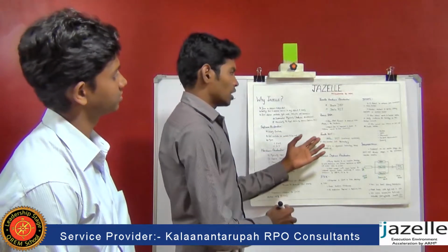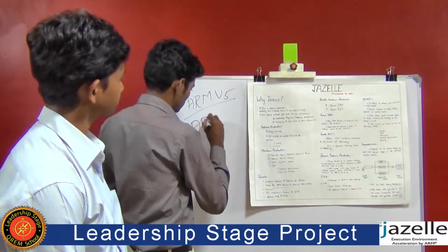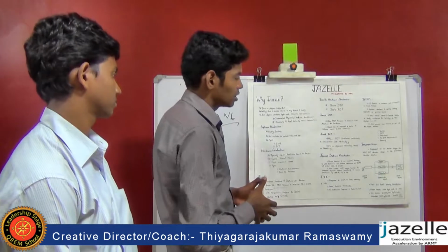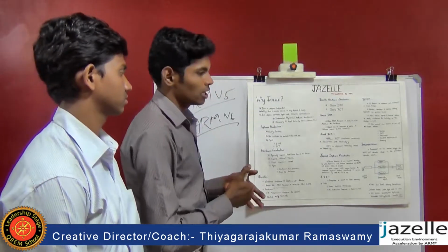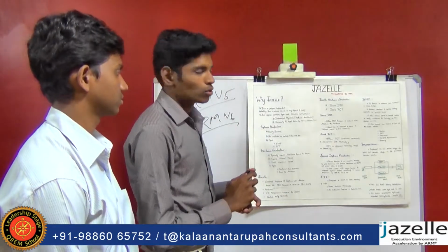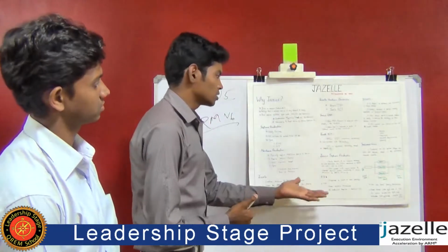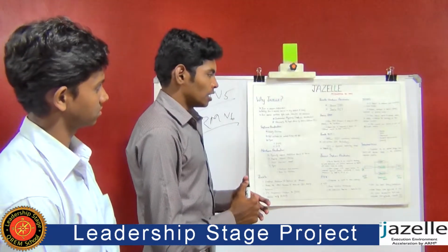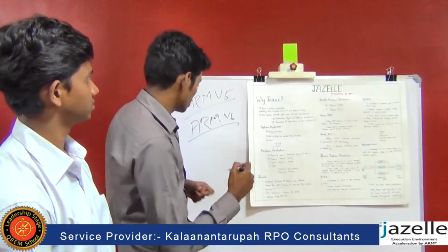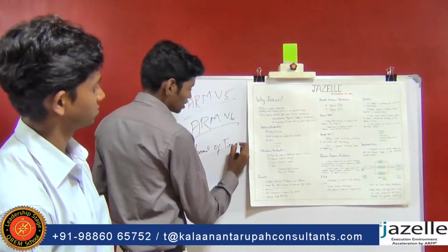Coming to RCT, ARM tried to implement the Jazelle technology in the ARM v6 architecture, but it is more complex. If you implement it, it will reduce the processing speed. So to overcome these problems, Jazelle RCT was created by ARM. RCT stands for runtime compilation target. It allows AOT compilation. AOT stands for ahead of time compiler.